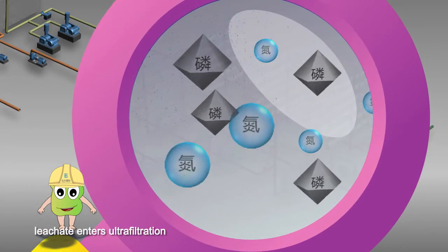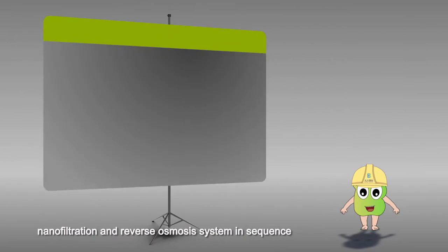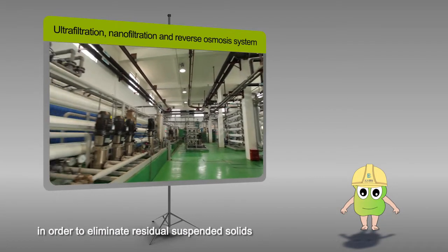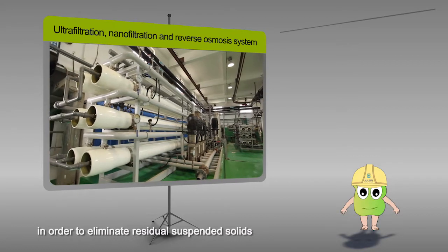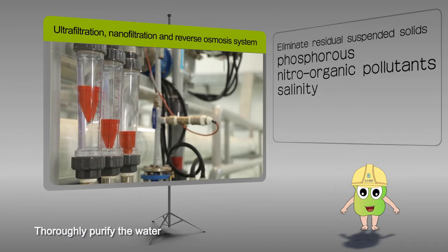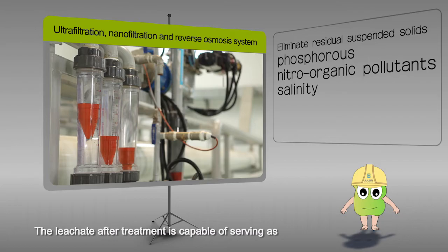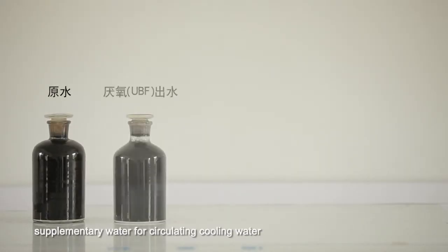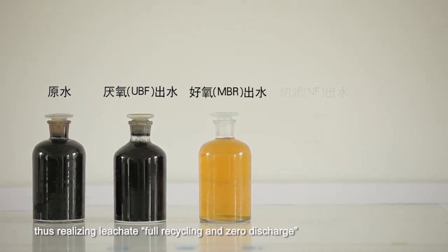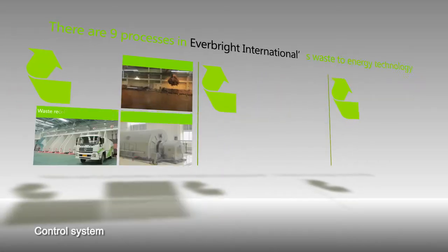Afterwards, leachate enters ultrafiltration, nanofiltration, and reverse osmosis systems in sequence in order to eliminate residual suspended solids, phosphorus, and nitro-organic pollutants, thoroughly purifying the water. The leachate after treatment is capable of serving as supplementary water for circulating cooling water, thus realizing leachate full recycling and zero discharge. 9. Control system.